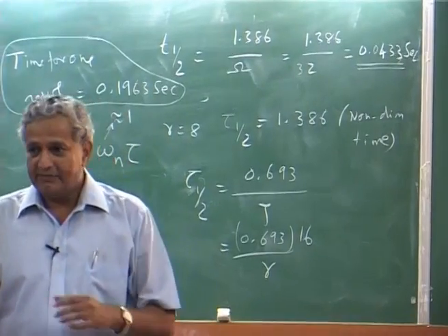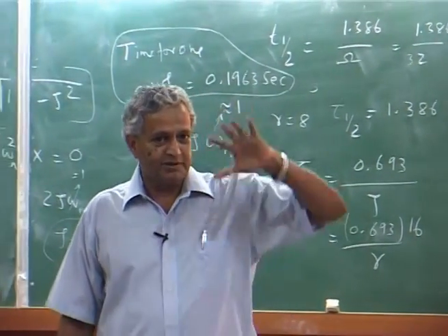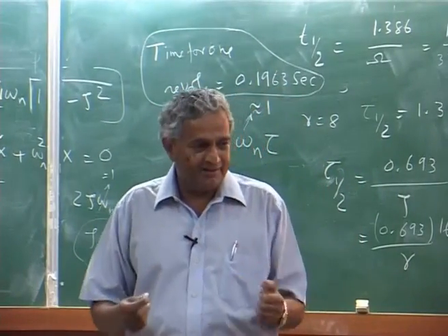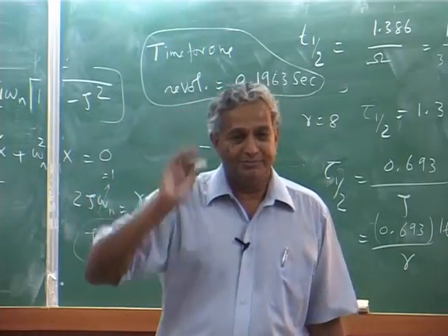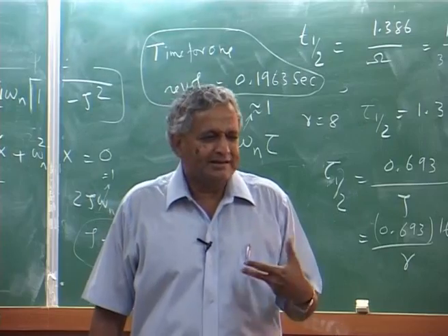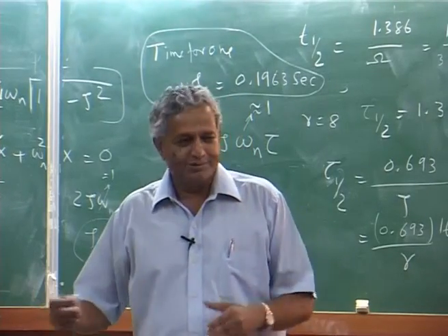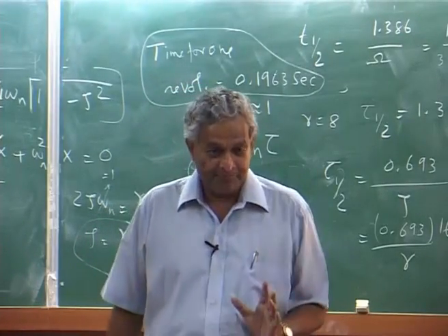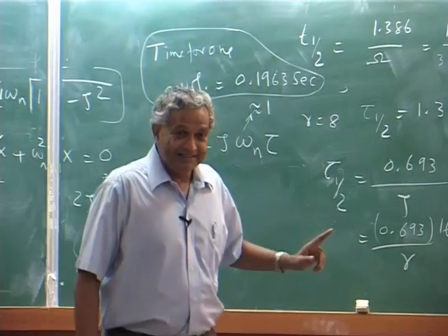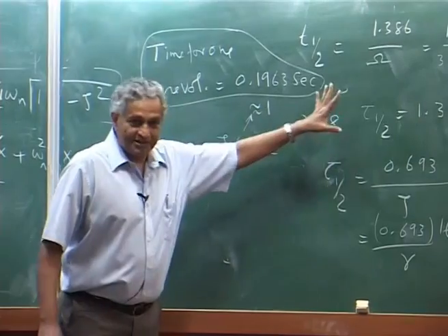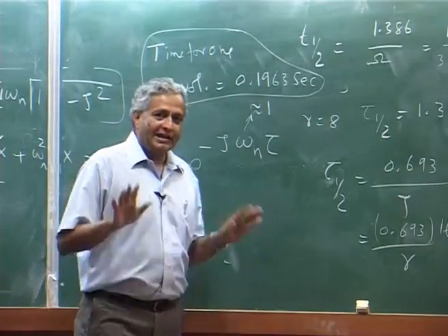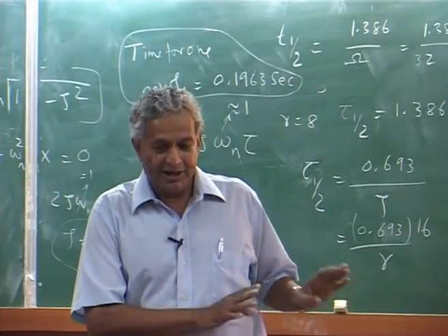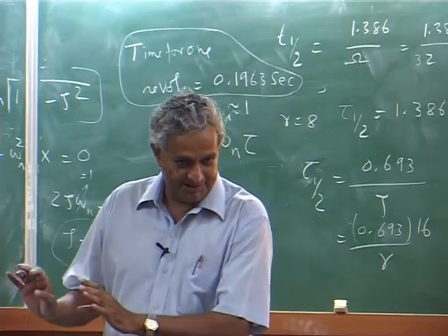That is why when the pilot gives any input, the response of the flap is quick. He won't recognize or feel a delay in the response of the blade. You can take it as though input output is instantaneous, even though there is a slight delay, but that delay you neglect. Why this is important is this particular number, I can now make an approximation, which is called the quasi static approximation.